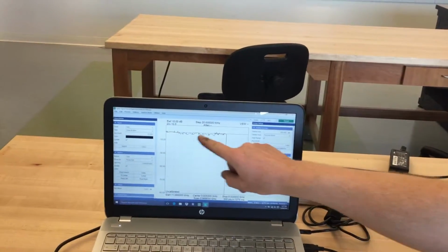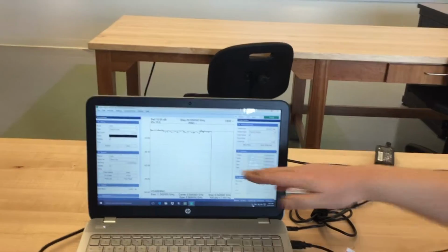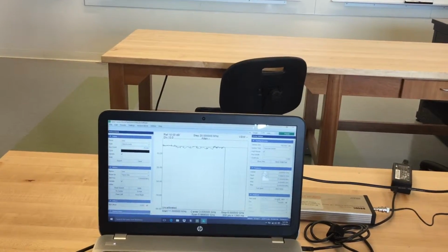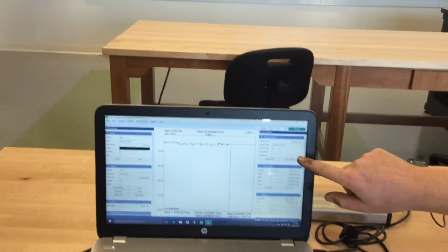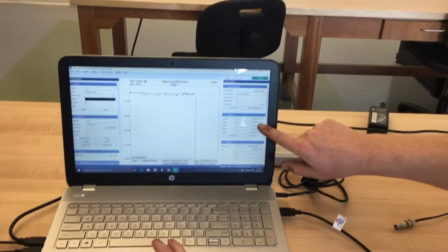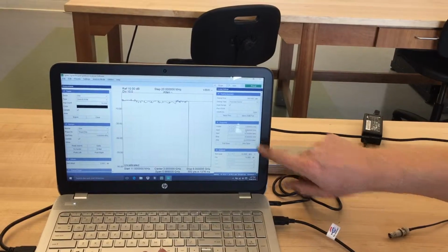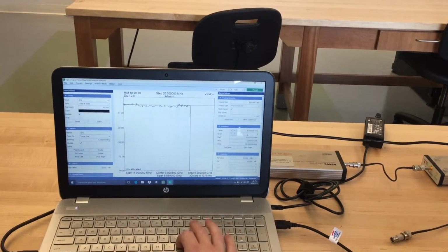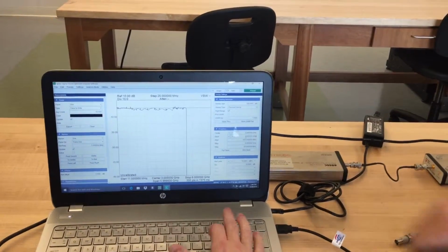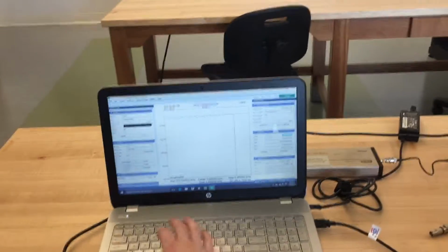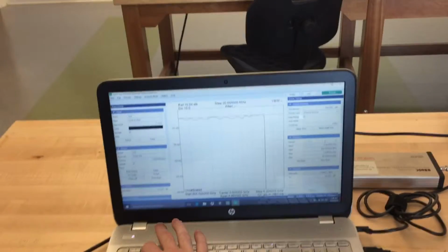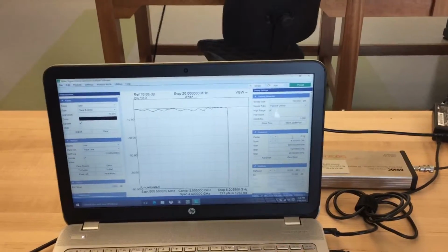Good. Now look at this raggy line here. We need to normalize this because the tracking generator is sending all these frequencies and this is what's being received. So I want you to put this span to be 4.4 G. And then put the center to be 2.2. Giga, right? G, yeah. Yep. Perfect.